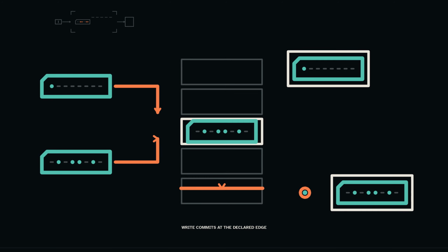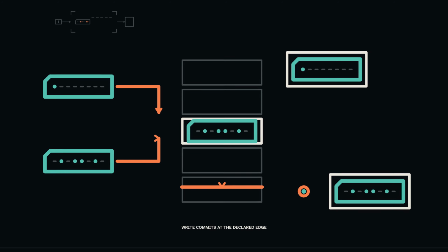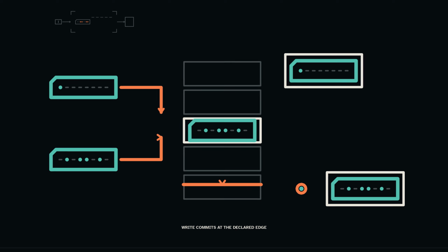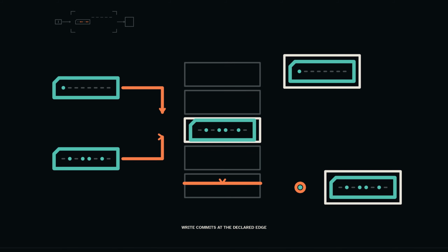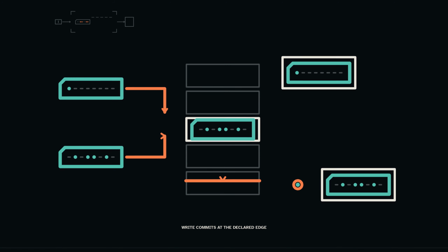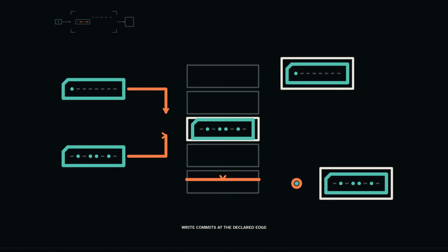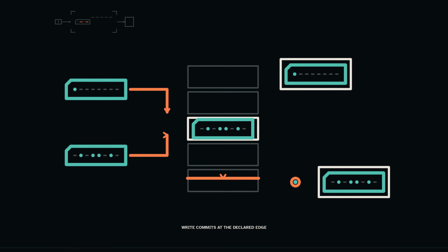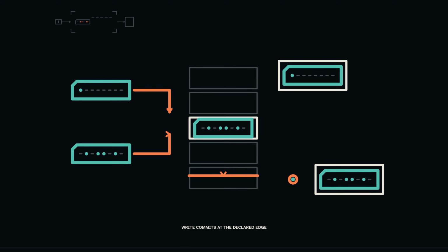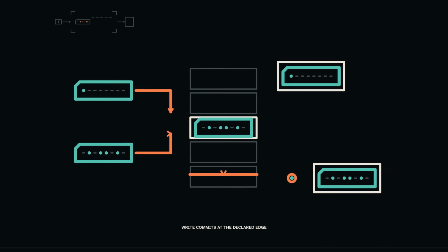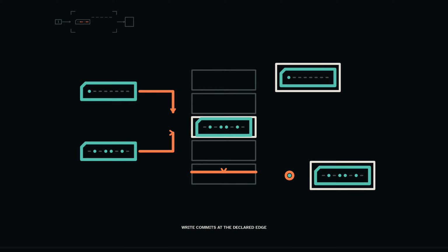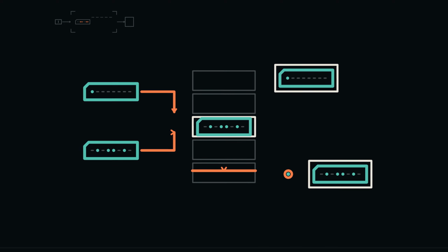Now the write control is active. MAR still selects address 80, and MDR still presents 5A. Pause before the edge. Which state is allowed to change? Only memory row 80. At the edge, that row captures 5A. Every other row preserves its previous byte. MAR, MDR, and R2 also remain unchanged. The ledger marks memory committed only on this edge. If write control were inactive, even with the same address and data, no row would change. The commit depends on selection, stable data, write permission, and the edge together.